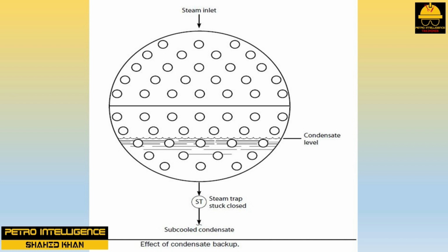If you think either of these two problems could cause a loss in reboiler duty, try opening the bypass around the steam trap. If the reboiler duty goes up, the problem was condensate backup. If the reboiler duty goes down, the problem might be a blown condensate seal. If it looks like a blown condensate seal problem, close the steam trap bypass. Then partially close the valve downstream of the steam trap. If this increases the reboiler duty, a blown condensate seal failure is proved.